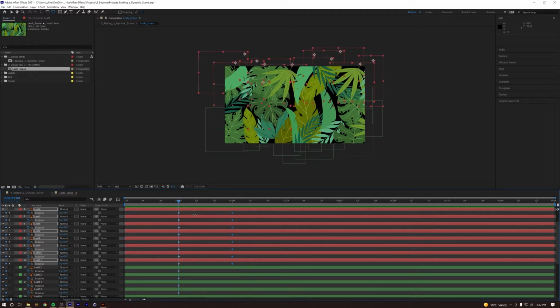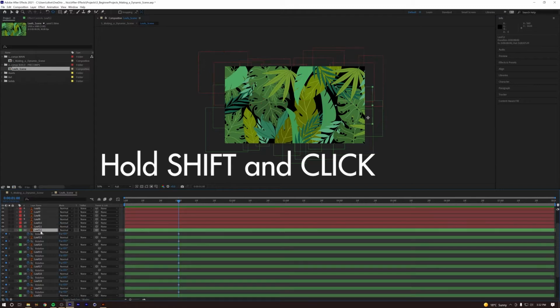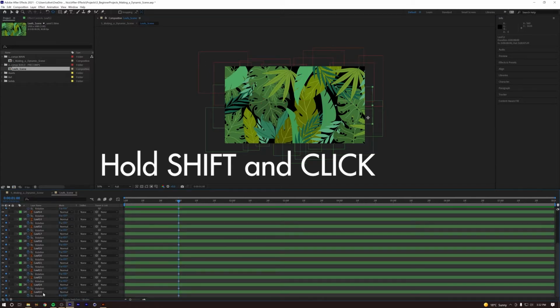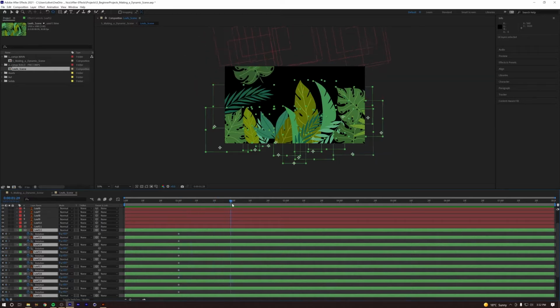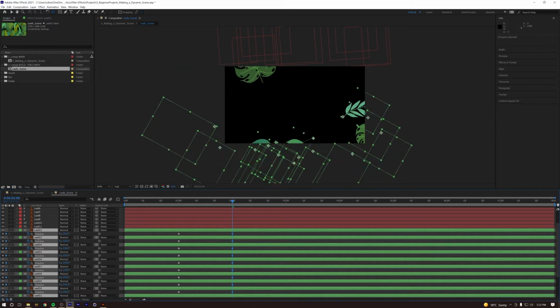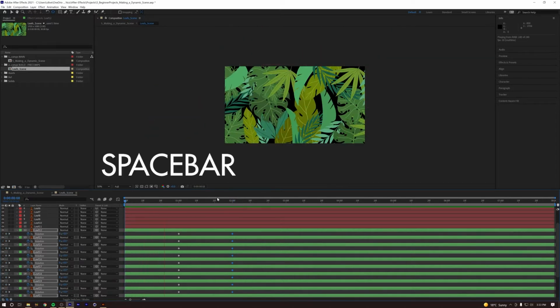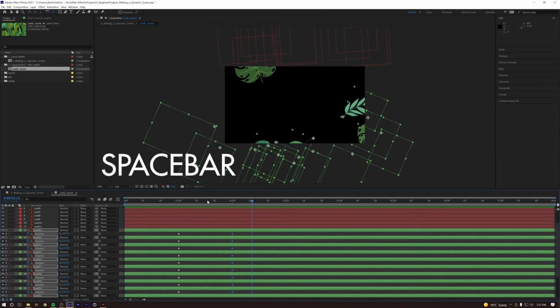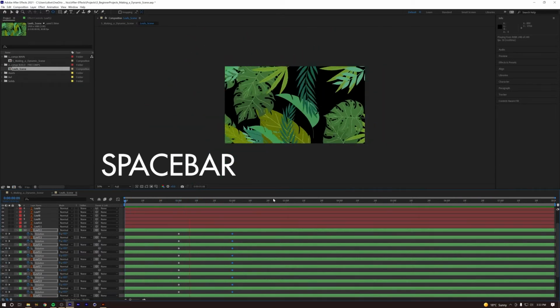And what I'm going to do now, you press U on these ones, it'll hide them, and then I can just see my keyframes for the bottom ones. Shift click on 12, and then if you shift click on 25, it'll highlight the bottom ones here. And if you go to the 2 seconds where these guys go off, I'm going to drag the other way. So if you do that, when you come back here and press play, you get all the leaves animating off, see? It looks like you're kind of going through, you know, the bush or something like that.